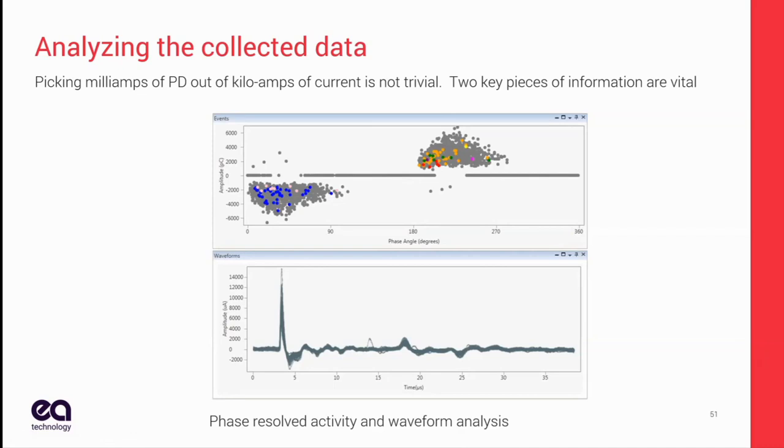Opposite polarities is really good, right? We got something on a positive half cycle and something on a negative half cycle. Each one of these dots represents a capture that we took. And so clearly something is going on in this picture that is synchronous with the 60 hertz, synchronous with the power system frequency, and is occurring twice a cycle and is opposite polarity. There aren't many things that'll do that. That's a very clear picture.